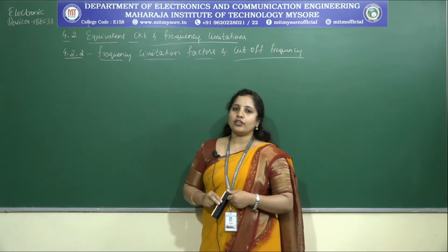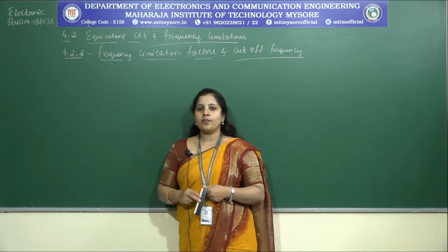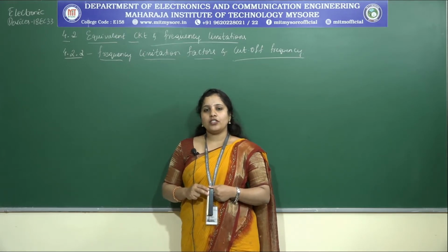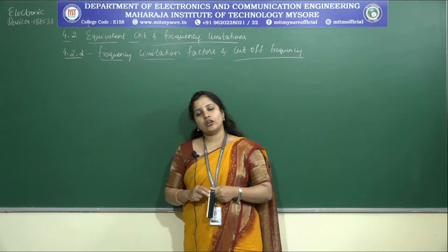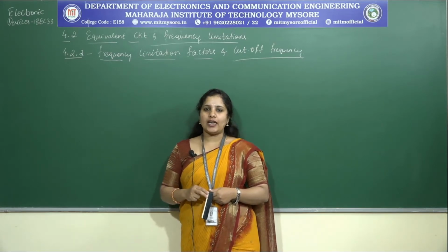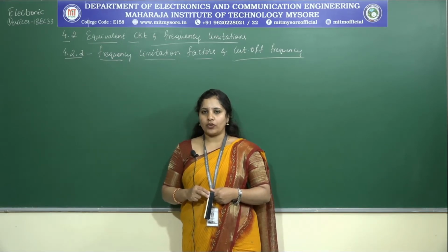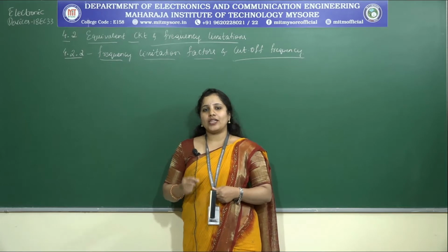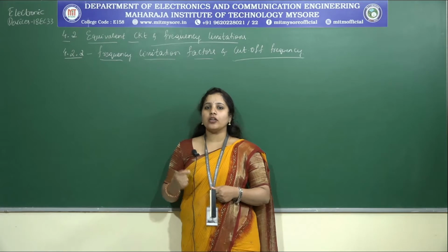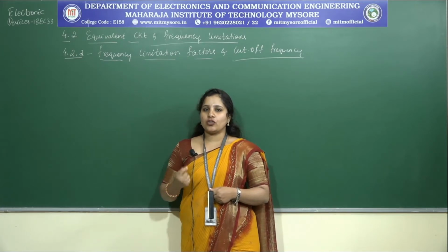limitation factor. There are two frequency limitation factors. The first frequency limitation factor was about the transit time, which is related by an equation L by Vs, where L indicates the length of the channel and Vs indicates the saturation velocity with which the charge carriers are moving. Now, when does this transit time become of prominence? Whenever we are dealing with applications of high frequency.